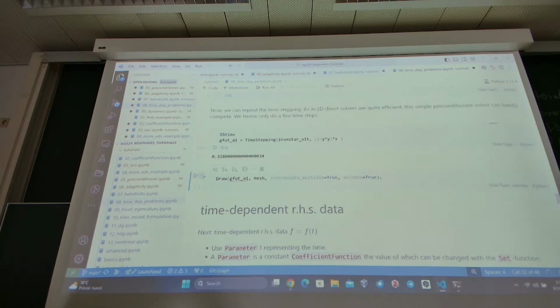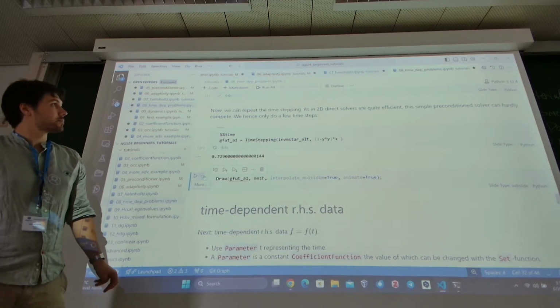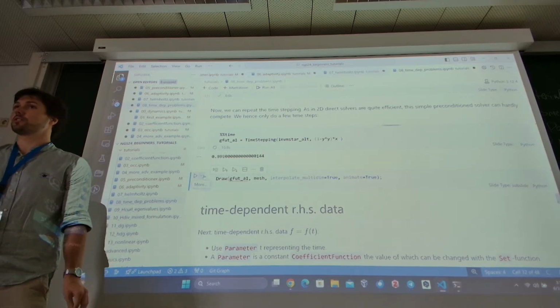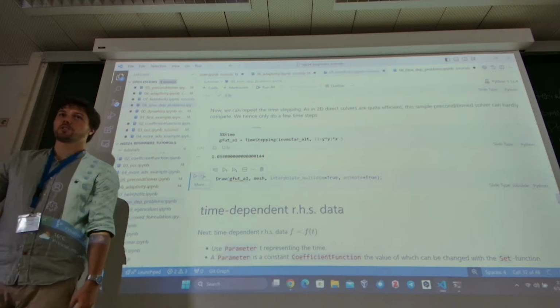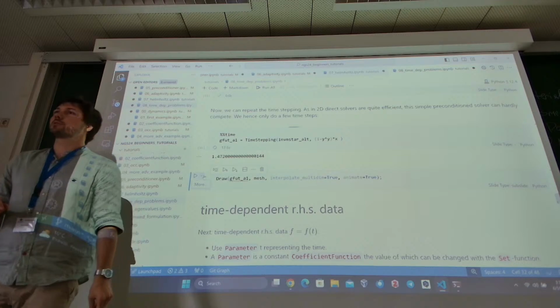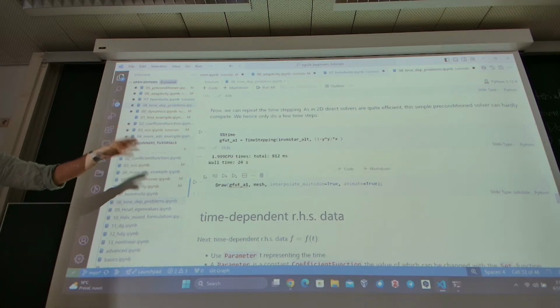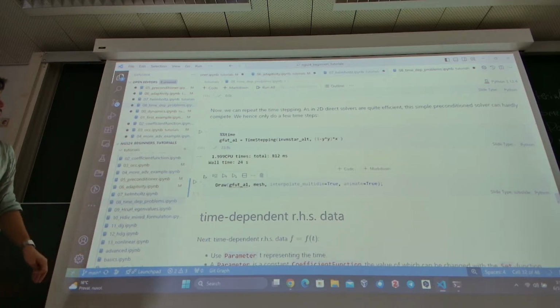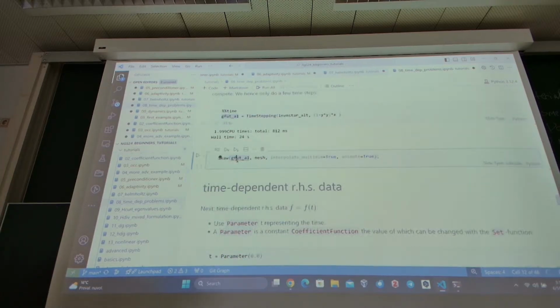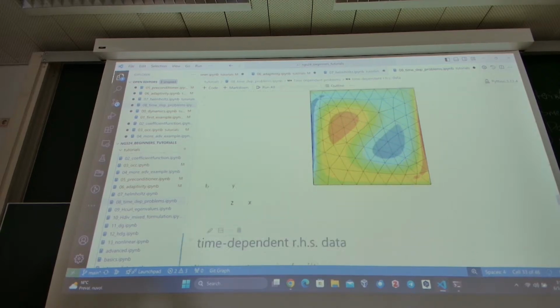This is going to be slower than the one before because we are using a CG solver on something that is not symmetric. As I told you before, there is the dispersive part that is symmetric, and then we have the wind, and the wind is non-symmetric. So you can play around and modify it so that you have a quicker solver, but it's just to let you know how to implement it using preconditioners. That took a little bit of time, but still we have almost, if not the same, solution.